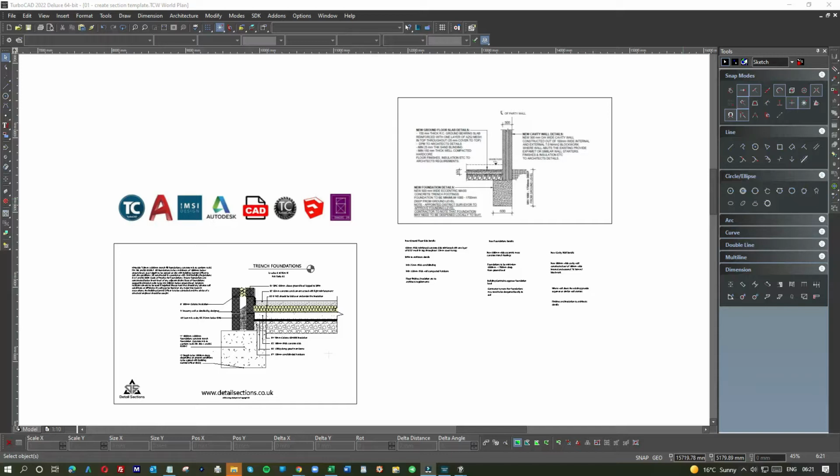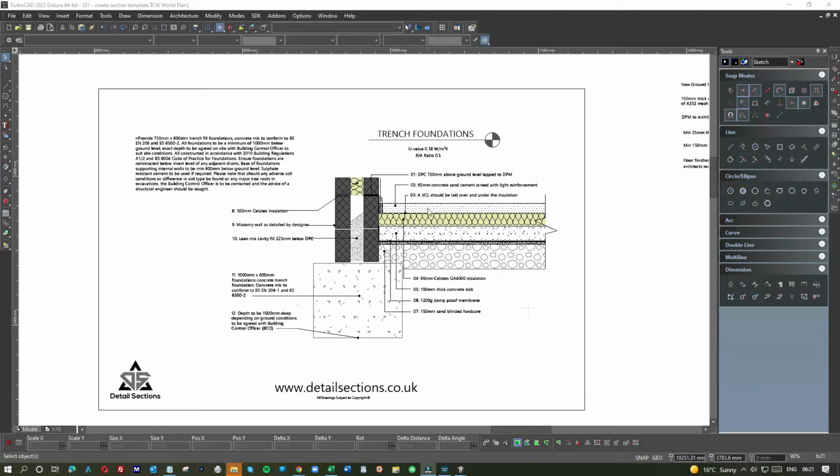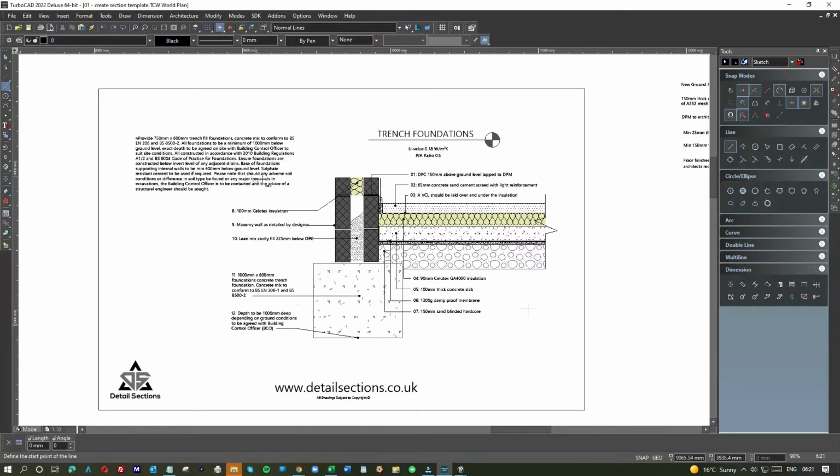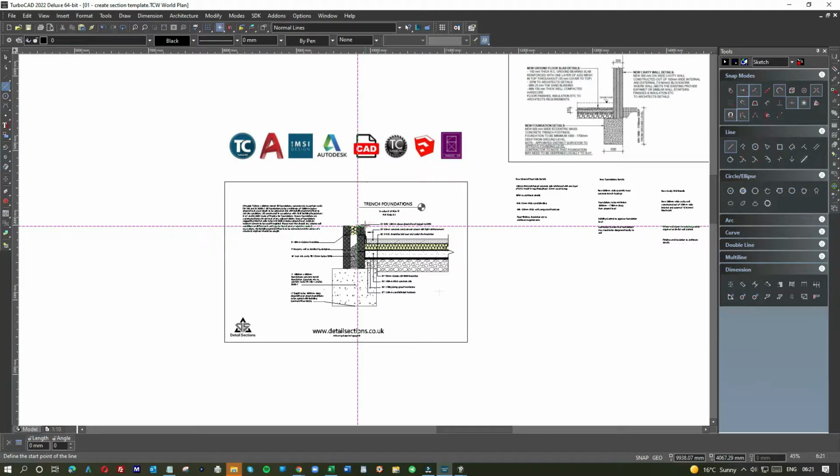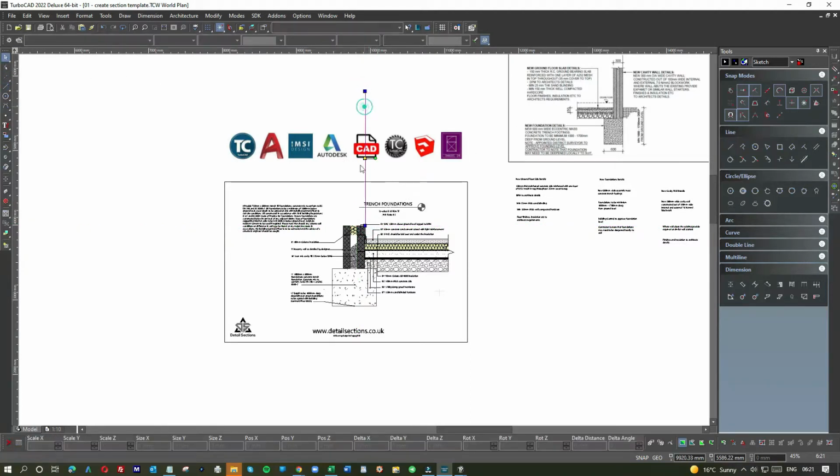legislation. When you build an extension on the back of your house, let's assume it's full width. What we used to do was trench foundations, say for a regular extension, which basically you dig down and place your wall on the center of the foundations, and that was right up to the boundary. So if I can give you an indication here, looking at this detailed section for trench foundations, let's assume that this was the boundary line between your neighbor, two houses.